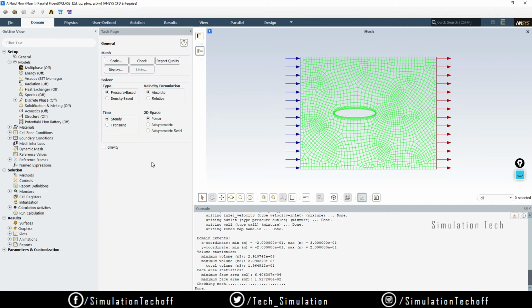If it is a liquid, like a liquid flowing in a pipe section, we can't compress that liquid. Okay, so for that we will move on to the density based one. At most stages, like 80% of problems will be based on the pressure based one, and only 15 or 20% will use the density based models.